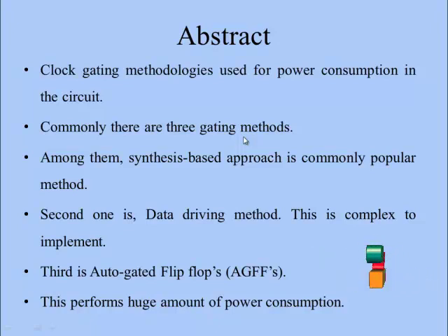If the triggering pulses are sufficiently narrow, the latch acts like an edge-triggered flip-flop, since only one latch, as opposed to two in the conventional master-slave configuration, is needed. The flip-flop is simpler in circuit complexity. This leads to a higher toggle rate for high-speed operations.